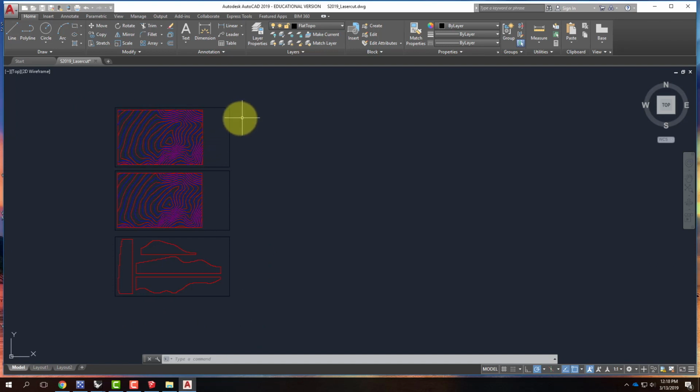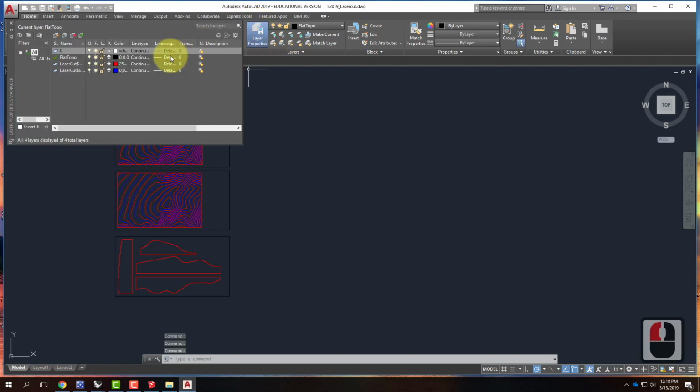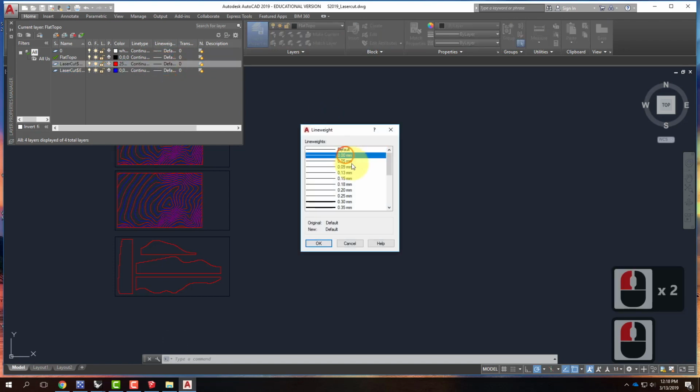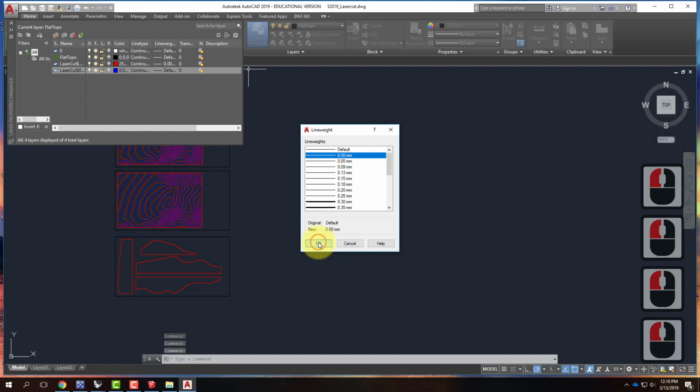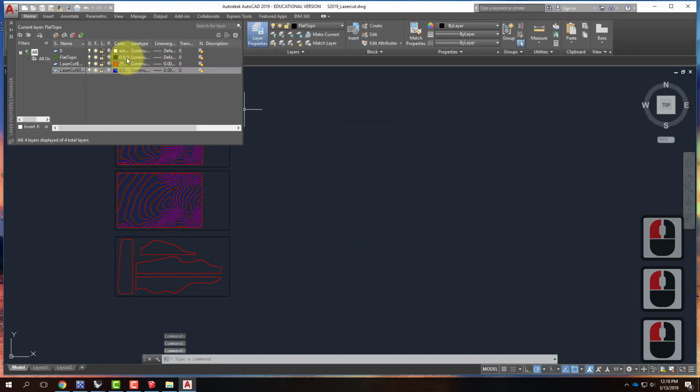The only thing that we don't have set already for us is the line weight that's necessary, so the thickness of the lines. You can do this over at the laser cutter machines, even in the viewer application that you do the cutting from. So you don't need full AutoCAD to do this. It's just a matter of going to the layer properties and changing these two layers, there and there, to have a line weight instead of the default. That represents a cut line in AutoCAD.